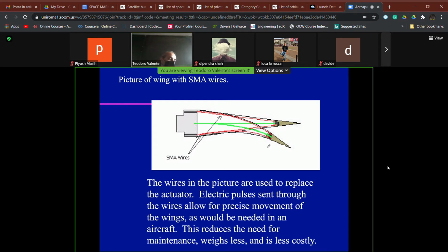Then, depending on the cooling way adopted, which can be forced cooling or natural cooling, we also have the cooling phase. And so we can have the thermal cycle, which can activate N-way, not one-way, N-way shape memory alloys, a cyclic behavior which responds to the design needs. So by using a current density, by letting current flow inside the wires, we can easily define and vary temperature, and we are also able to model it. We will see one example later on, without using a furnace.